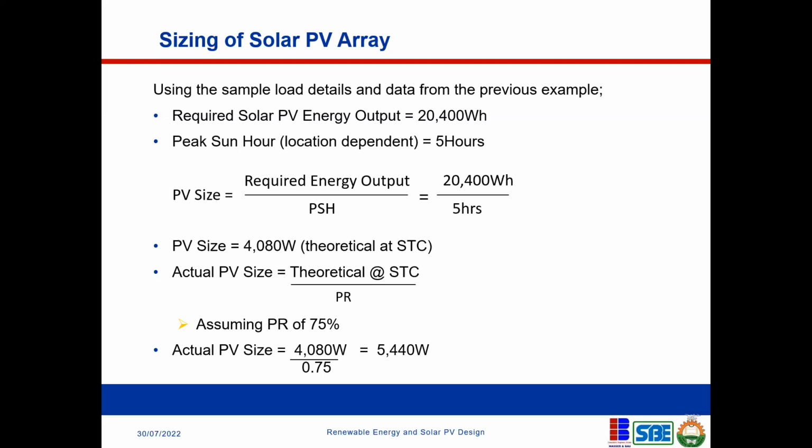How do you test the capacity of the module you are buying, technically? You may need to test the voltage and the current that it is producing. You can go with your multimeter, take the voltage and the current that it is producing, and compare with the rating that is given on the PV panel. If you're in Lagos, you can come to Pan Atlantic University. We'll test it for you, free.